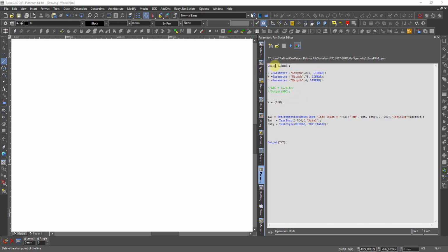I have the units, because I'm an English system, and then we need to force it over to millimeter. That's what this does. And this number 1 there, that is the scale factor. So if I want to draw in 1 to 50, then I set this to 0.02. Then we draw in 1 to 50.